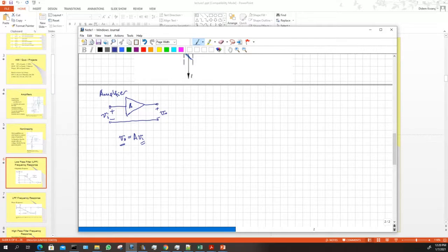One thing about amplifiers is they amplify the signal, they will also amplify the noise. So remember we talked last week of signal to noise ratio. Signal to noise ratio was the power of the input signal divided by the power of the noise that's affecting your system, right? So the bad thing. Now the amplifier can't tell the difference between your signal and your noise.